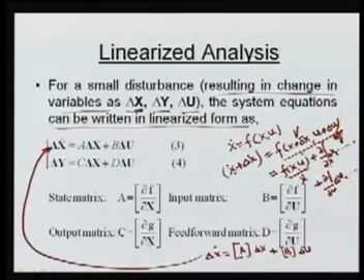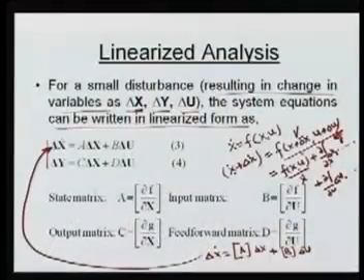This is nothing but our equation linearized. So what I did: we are perturbing our state and our input, so there is a small change in delta x. We are differentiating this nonlinear function, and finally we get this value at a certain point. So this A will be the partial differentiation of function f, in the previous case, over the state variable. So this A is called the state matrix.